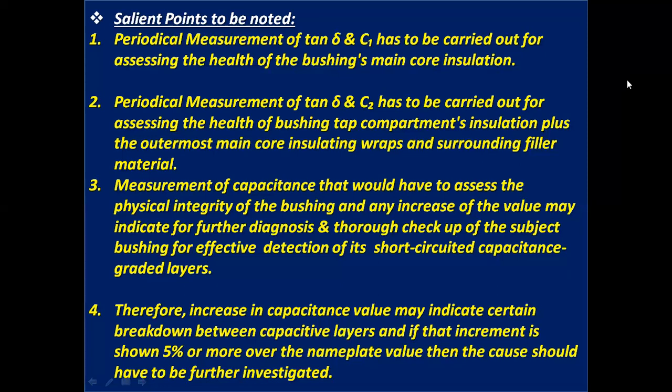Therefore, an increase in capacitance value may indicate certain breakdown between the capacitive layers, and if that increment is shown to be 5% or more over the nameplate value, then the case should be further investigated.